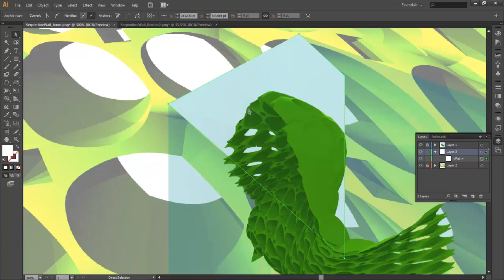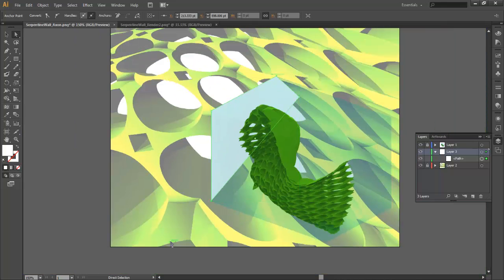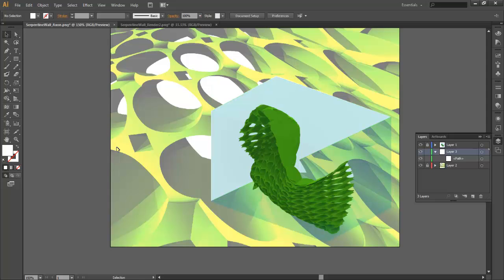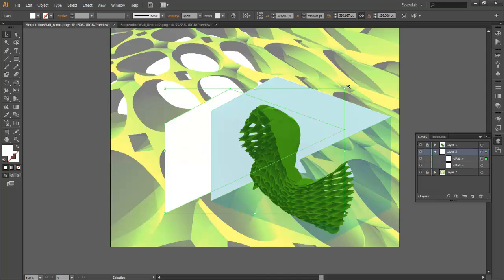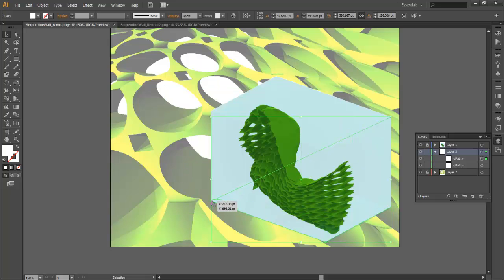Then I can maneuver and position that over there. Okay, and because this is an axon, this is a symmetrical geometry, so I'm going to hit Control C and Control V, and rotate that around 180 degrees, grab the anchor, and move it into place. You'll note that I'm back on the regular selection tool, V, when I'm doing that. So that's how these two tools can work together in concert with each other.